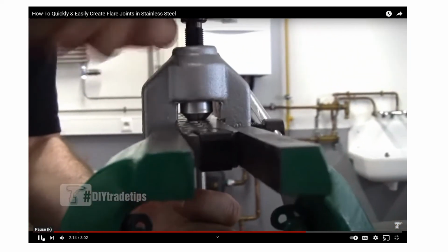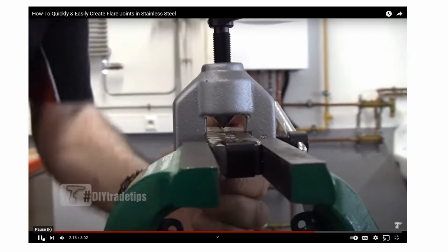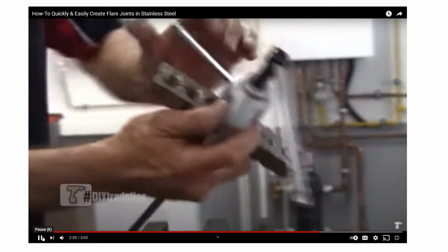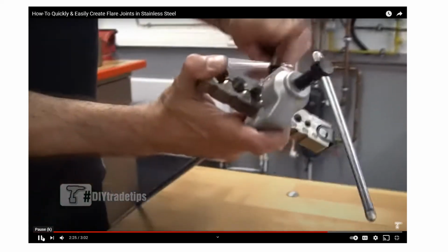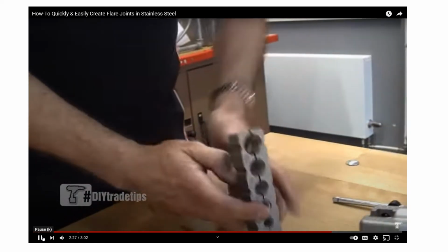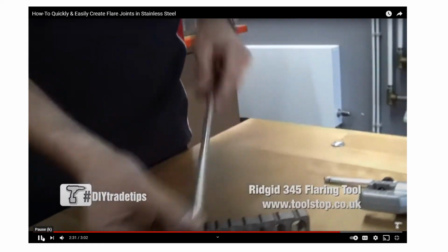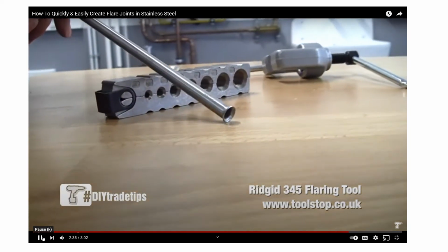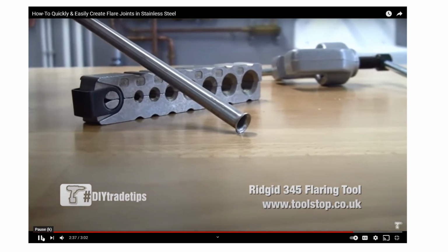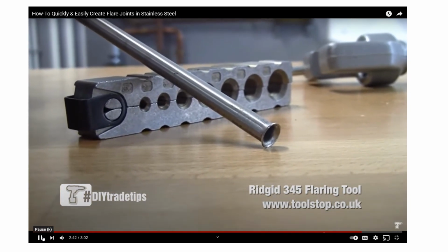Okay, back it off. Open that up all the way. We'll just take him out the vise, slacken off the flaring block, take them out, open up. There you go, 45-degree flared end. So that's ready now for your cone fitting to go on there and make a joint. So that's the rigid 345 flaring tool.